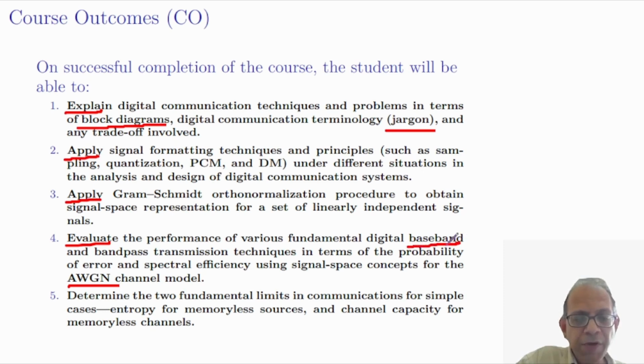By baseband, we mean that the original information is transmitted in the original lower frequency band, whereas bandpass transmission implies that the signal is used to modulate a high frequency carrier for transmission.